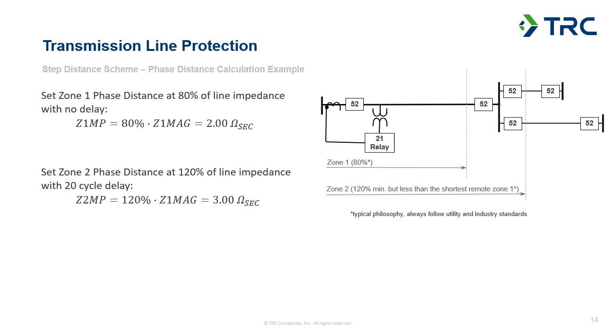But we also put that line impedance information into the relay. So many relays already know what that line angle is, and by default set the impedance characteristic to align with the line impedance angle. Anyway, there are some varieties out there that you would set that separately, which you certainly can do, but in many relays, it's done automatically.